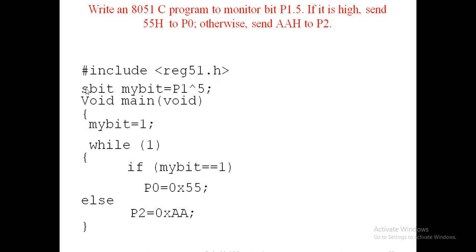Next I am using sbit. sbit is a keyword or data type used to access a single bit in the SFR memory organization. So P1^5 is assigned to my bit. You can give any other name also, no issue. mybit is equal to P1^5.